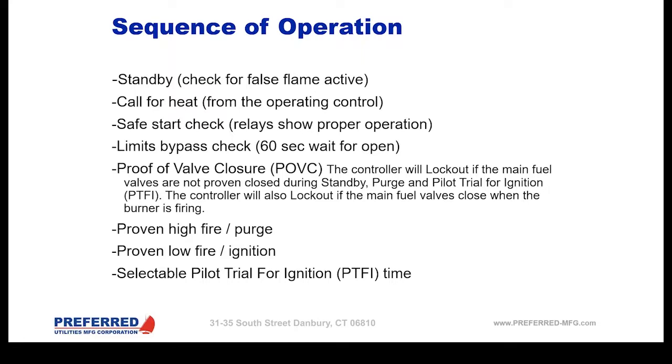So we have to see proof of airflow within a certain number of seconds. That changes depending on the flame safeguard, but usually it's about 60 seconds that all those limits have to be made, okay? The proof of valve closure has to be there, so we know that that valve is closed, okay? Then we've got to go into a purge condition.